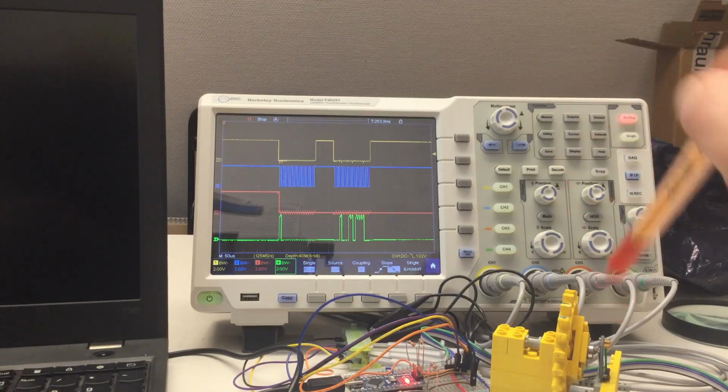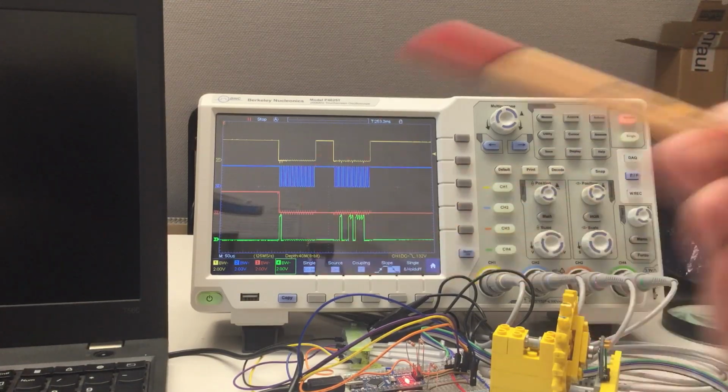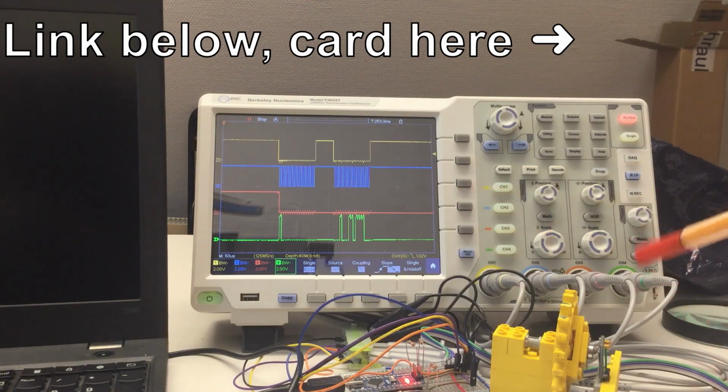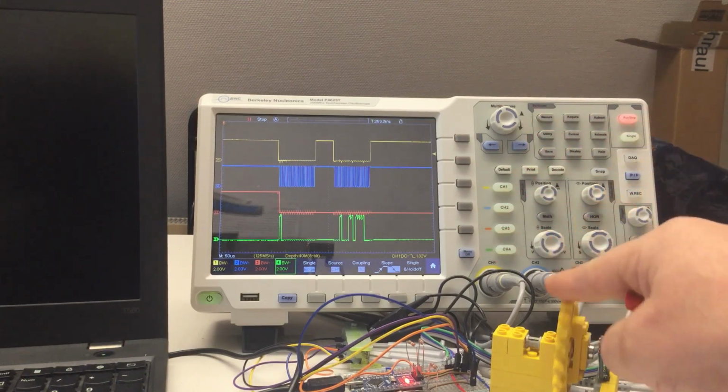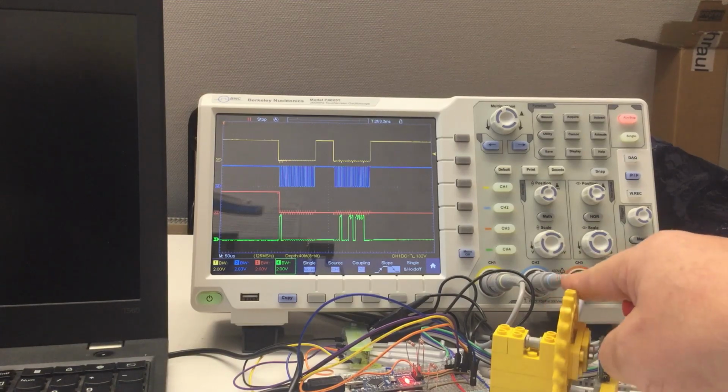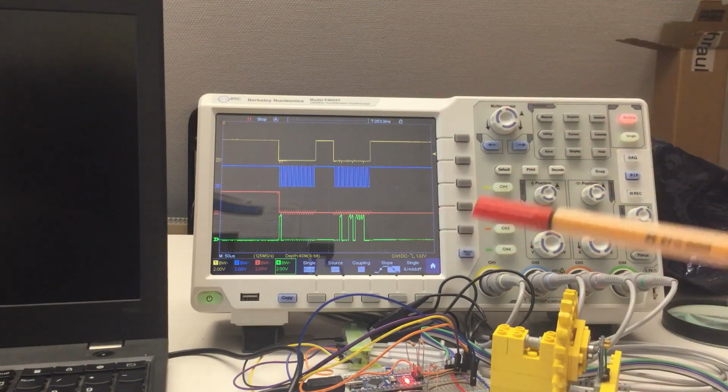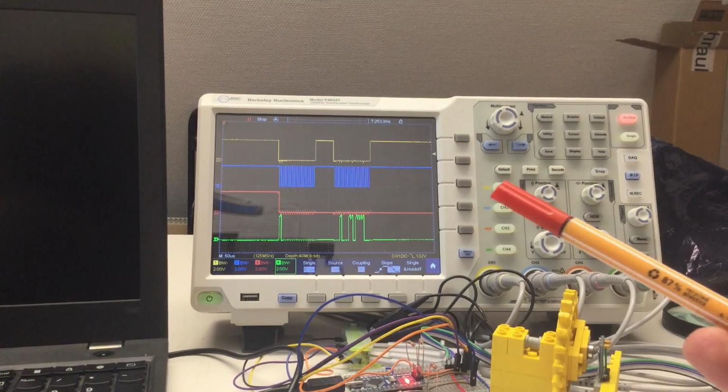Because especially that chip here is, I mean, that's an obsolete chip. I told that in part 1, but similar chips and the successor, the A1335 from Allegro, are, for example, used to measure the position in the power steering in your car.